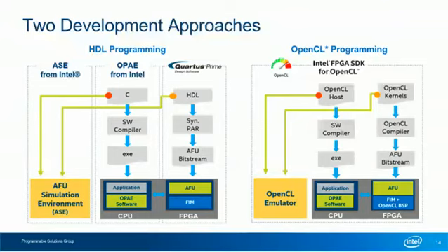The SDK, with the help of traditional software compiler, will also generate the appropriate software code that is run on the CPU. Users will need to know the OpenCL host API and not the OPAE interface. Before creating the actual bitstream, the OpenCL flow allows users to emulate the OpenCL C kernel on x86 machines to easily perform functional debug. This flow is more productive of the two.